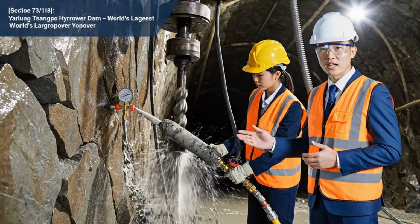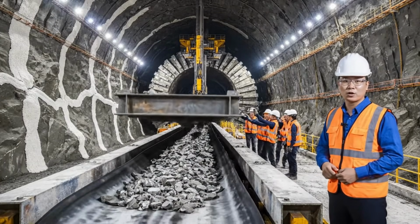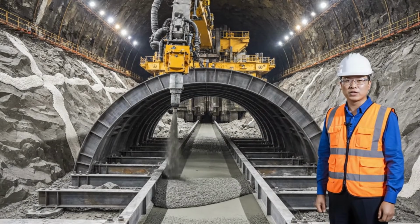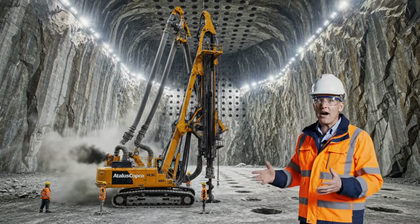The probe drill advances, retrieving core samples for assessment. The cutter head advances at a reduced speed through the stabilized fault zone. The treated material cuts cleanly, revealing the grout-filled fractures in the muck. The drilling jumbo you see here is boring 4-meter deep blast holes at incredible speed, preparing the rock for the